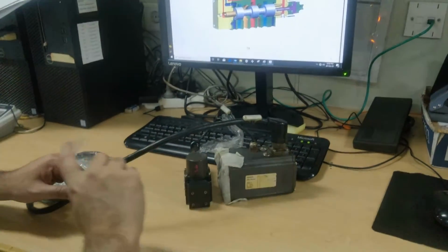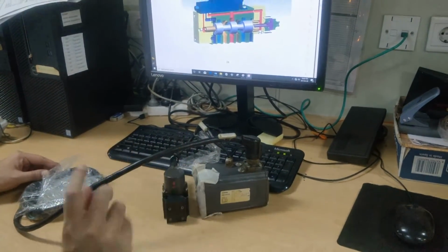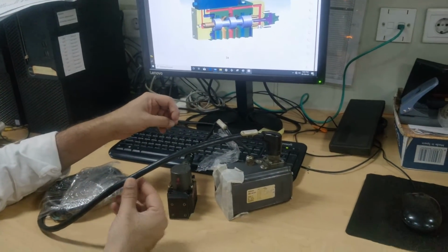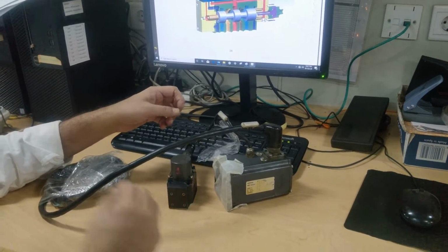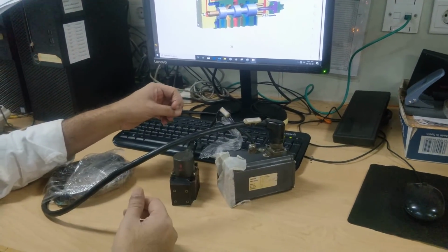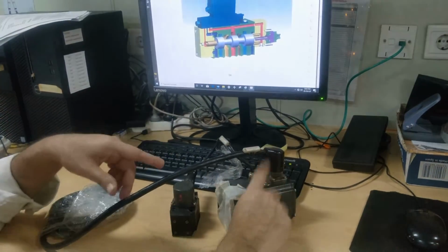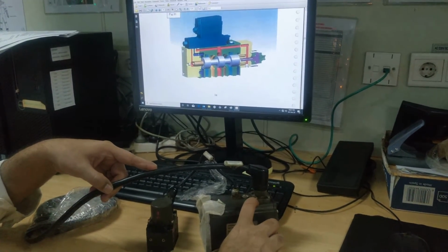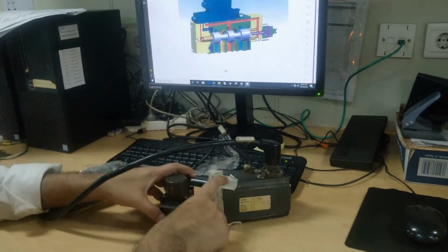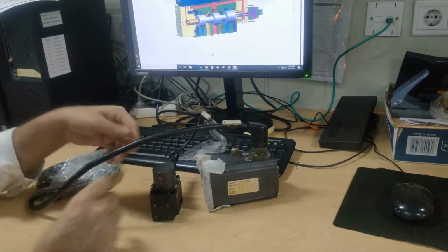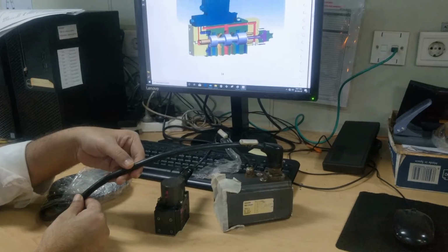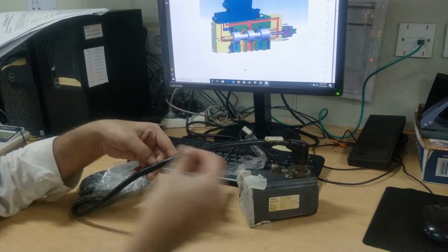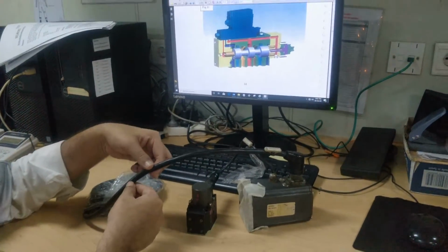From the MPC the signal is coming here. These are all multi-core cables, guys, so a multi-core cable has multiple functions. It gives the input and also receives the feedback. The signal comes from the J70 port, and from here it energizes the solenoid. This is a milliamp signal coming from the MPC. I will show you in the input output channel how the signal transmission is happening.